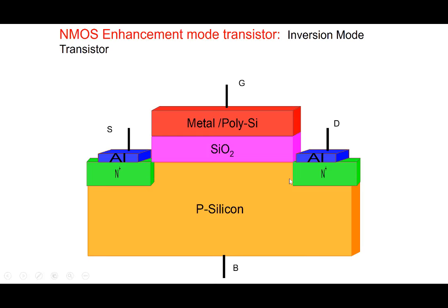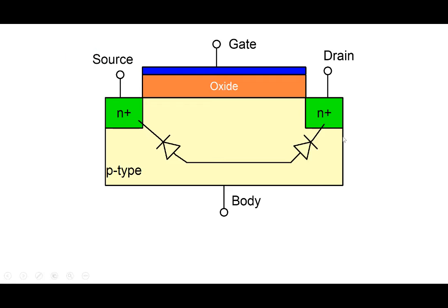So let's see how this particular device operates. This is a simplified schematic of our transistor, MOSFET here. So again, there is a gate, metal here, oxide here, P-type semiconductor here, N+ region source, N+ region here drain. In this case, the source and the drain can be interchanged. So it's a symmetrical device. And note that because the body is P-type here, there's effectively a PN junction here. N+ P is a PN junction. And there's another PN junction here at this particular point.